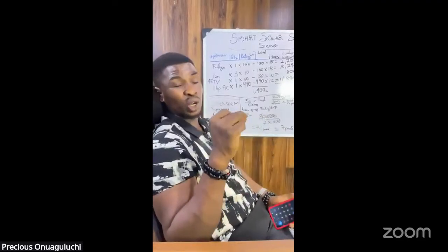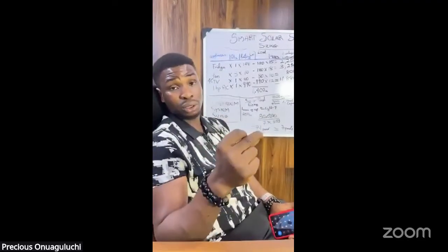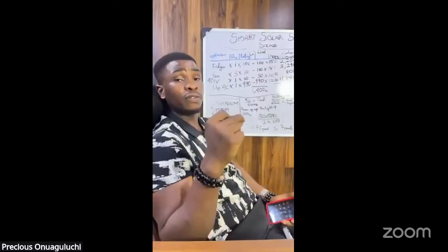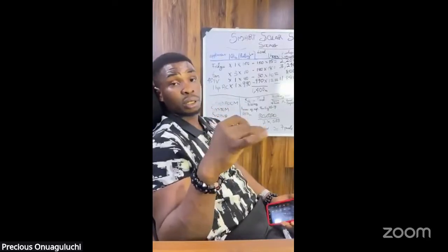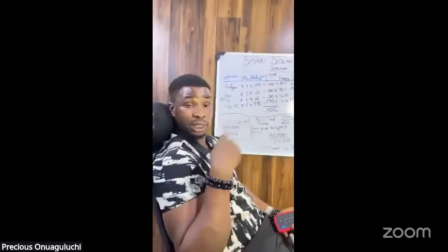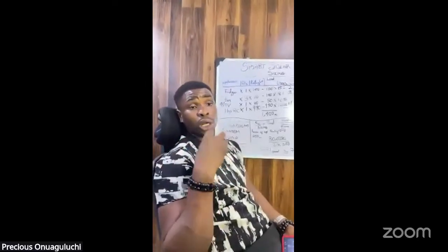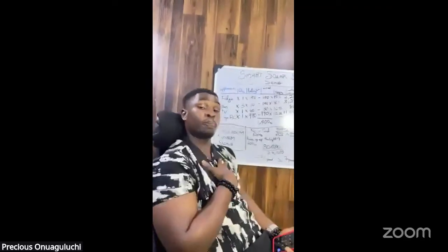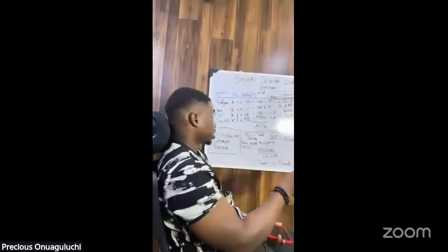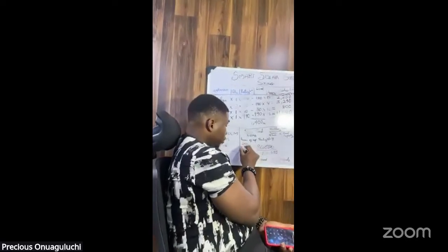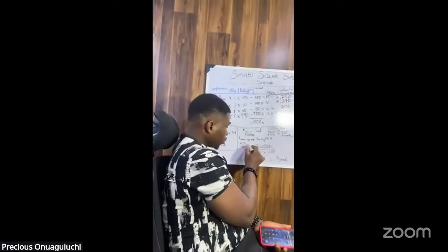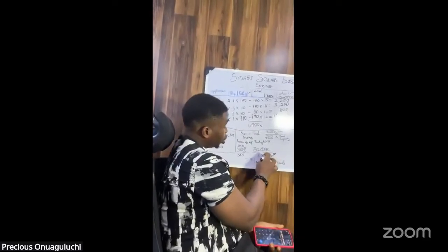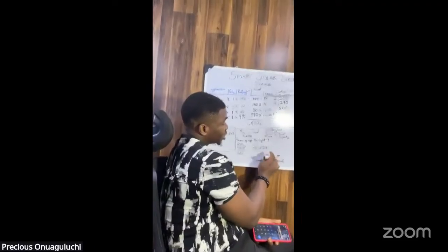But remember, when you're on site, in real life scenarios, it's not an ideal test environment, right? So if you can get 60%, it's an average. Remember, you have dry season in Nigeria, talking to our Nigerian customers, you have dry season, you have rainy season. So what you're looking for is an average figure. In my own personal calculations, I use 60% of these 600 watts, right? So while I do my calculation, I assume that the panels will produce 360 watts of power.